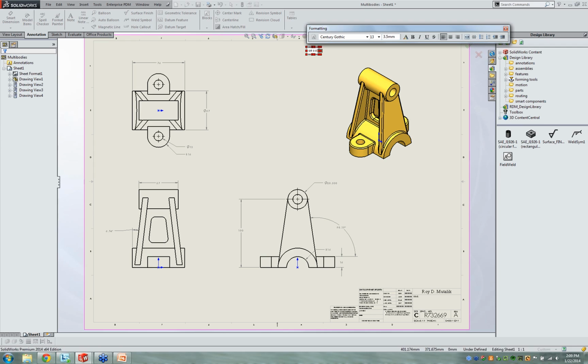So I'll say that, all cosmetic. I'll go ahead and type that there, and I'll make it a little bit bigger just so that we can see what's going on. All right, so that's our note here. I did do one thing wrong. I typed this in lowercase. I'm sure many of you have the same practice that we have here at DesignPoint. All of these notes should be in all uppercase.